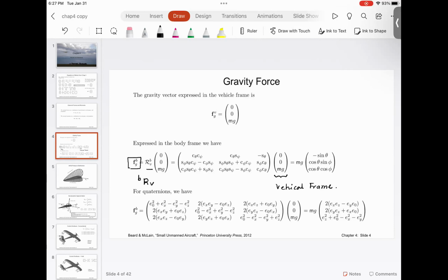Unfortunately, you do not have any acceleration measurement in the yaw direction. So you cannot find out the value of yaw from this equation, but you can certainly find out a value of pitch and roll from the acceleration values.